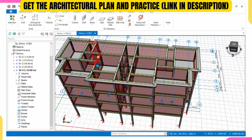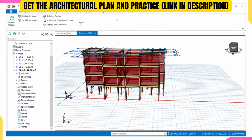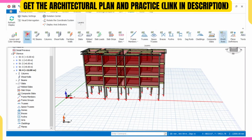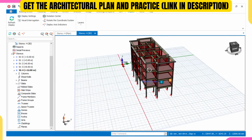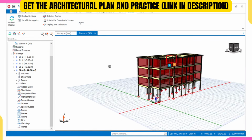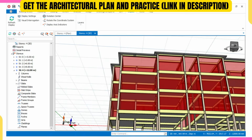So let's go over to our 3D view. So this is what we're having now. Okay, let me turn off everything. I'll come to display, come to layer, turn off axis, turn off ghost axis, turn off print definition, and turn off my text. So this is what I'm having right now. We have successfully modeled this, we are through with our modeling, with our parapet load intact.